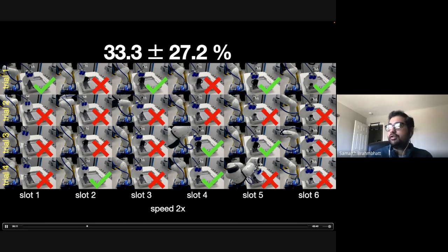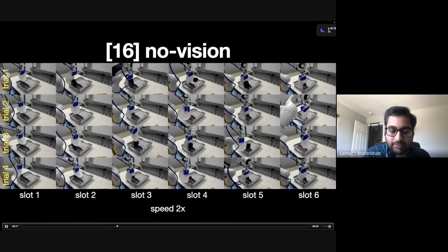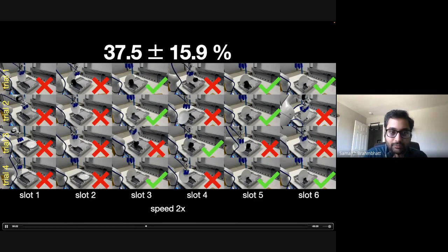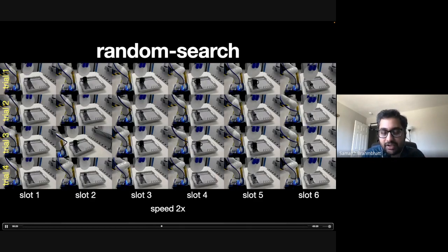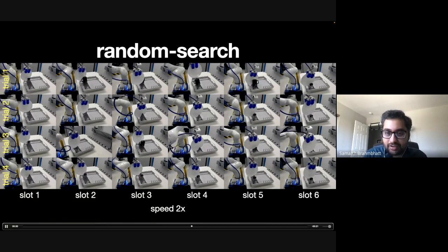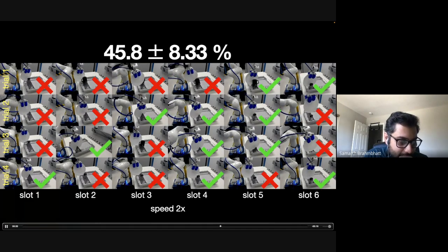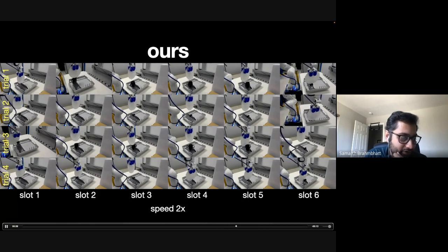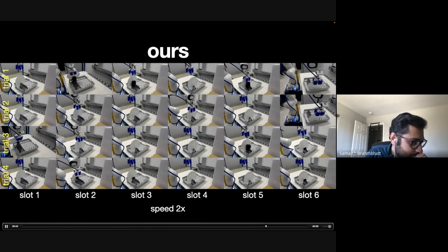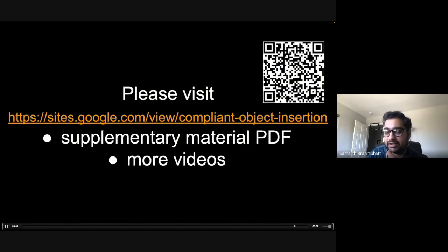Yeah, that's a good question. For example, the delay parameter, the range for how much delay we want to randomize, some of that can be done by system identification, right? We can execute any kind of dummy policy on the real robot and see what is the round trip delay and identify that. But for the larger question about identifying the other hyperparameters, at this point, it's mostly a question of trial and error.